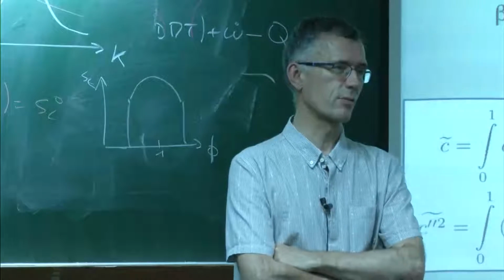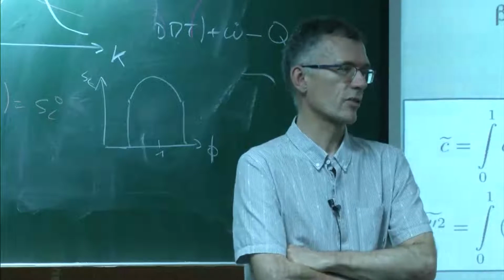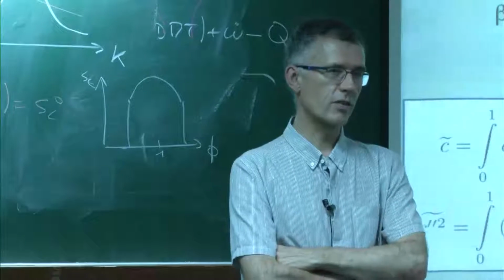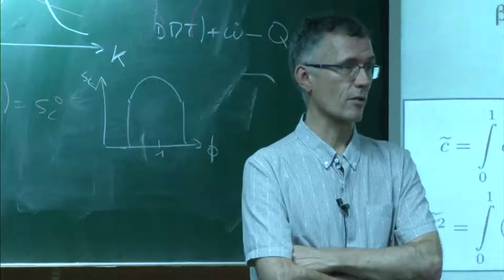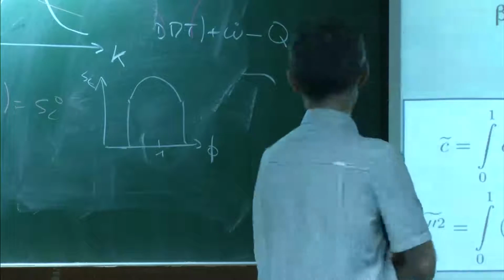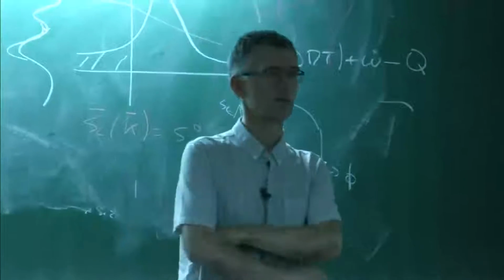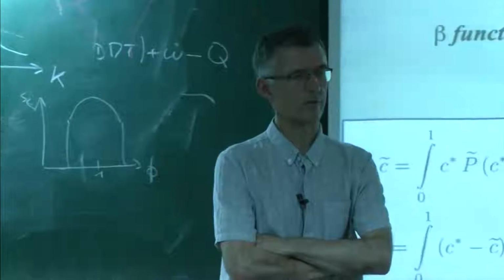It's true that for piston engines, it's bad luck. I mean, you guys pulled the wrong case. It's really the most difficult case. You have everything at the same time. Much easier to do a gas turbine. So in piston engines, people are still fighting to imagine what could be the model. At the moment, ECFM3Z is really the basic standard that you find in most codes. Even Converge will have it soon. So that's probably a reasonable choice.